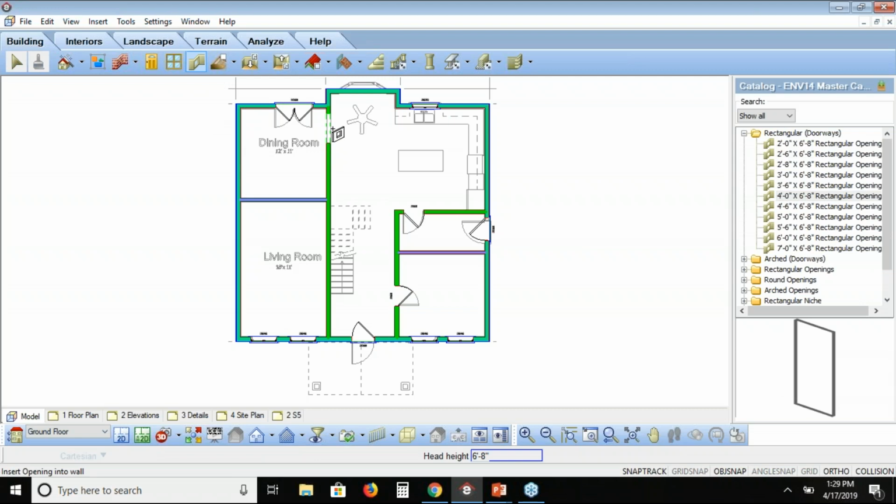So if you don't supply the windows and doors, but still need to cut that hole for openings, just put them in as an opening. And that opening will do the exact same thing. It'll also case around them as well, following the rules of the trim that we set for the individual walls.